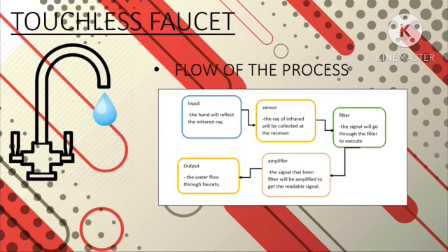For the result, the fundamental goal of the non-inverting op-amp arrangement is to significantly amplify the input signal without changing its phase. The ratio of the resistors in the feedback loop determines the circuit voltage gain.